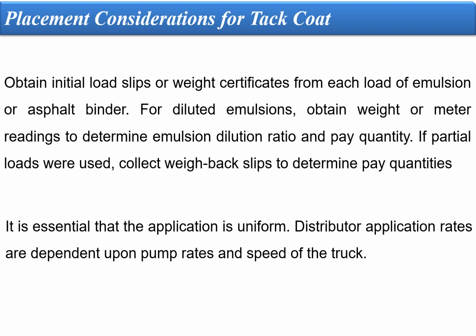Distributor application rates are dependent upon the pump rates and the speed of the truck, which is generally fixed during the trial sessions in order to confirm what should be the speed of the truck and what should be the pumping rate with which the emulsion is being sprayed on top of the surface.